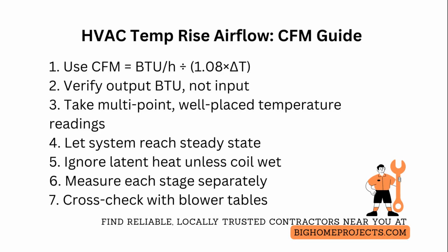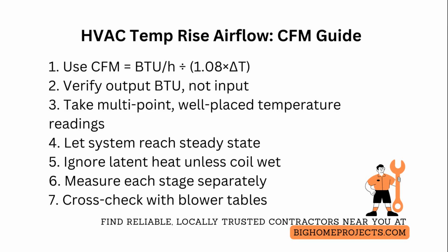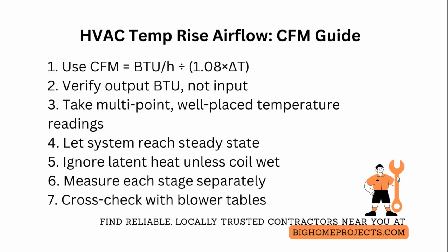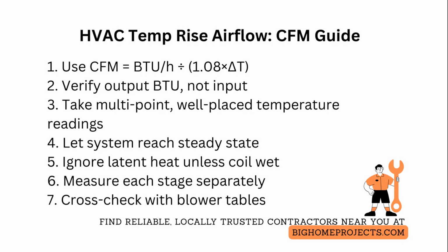Cross-check the calculated airflow cubic feet per minute against external static pressure and the blower performance table. If the math says 1,100 cubic feet per minute, but the table at measured total external static pressure shows 800 cubic feet per minute, your measurements or assumptions are off. After testing, restore the duct by sealing any sensor penetrations so the calculated airflow cubic feet per minute still matches what the blower actually delivers in a tight system.